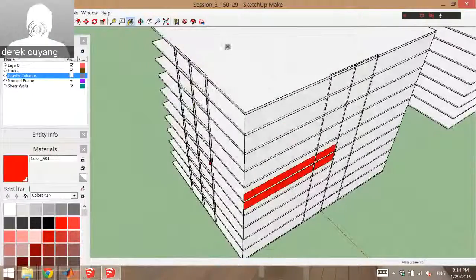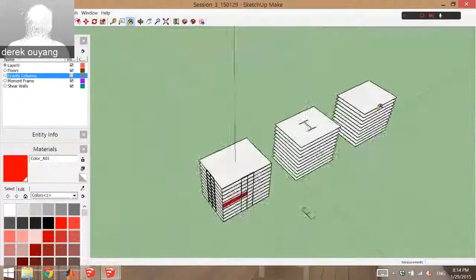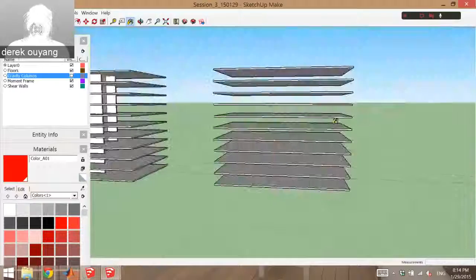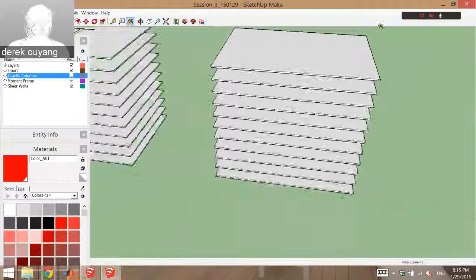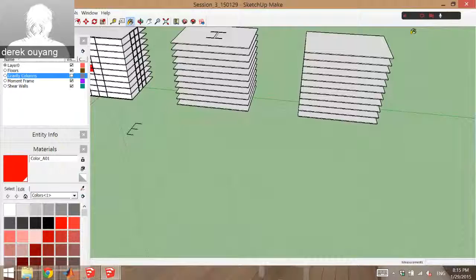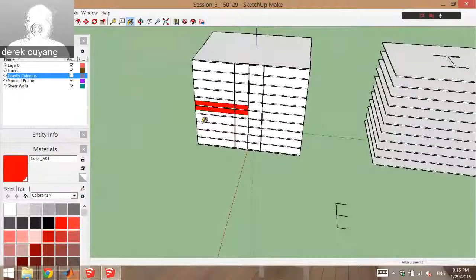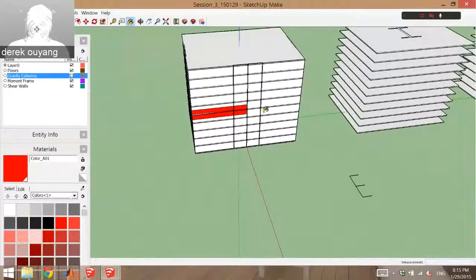And of course, if this was placed somewhere else or there were three of them, then one of the things you might decide in your option is to add more moment frames and just get a sense of proportionally what that does to your members. You're going to be dealing with a lot of situations where you're trying to downsize things, right? It's just like you say to the architect, there's no such thing as a W 5 billion, right? And so you've got to break that down into multiple systems, into multiple frames that are acting, extend it as far as geometry will allow you to, add bracing where you can to increase the stiffness. Those are the only choices you really have once a tower is set in its geometry.